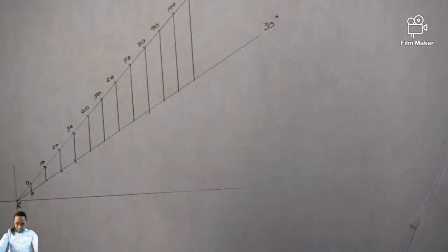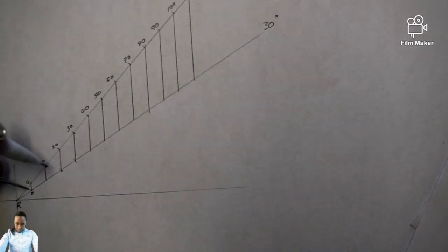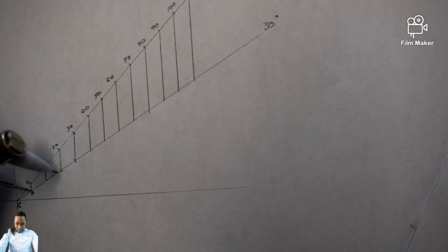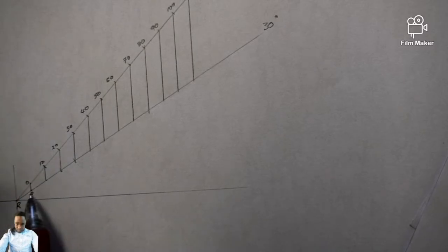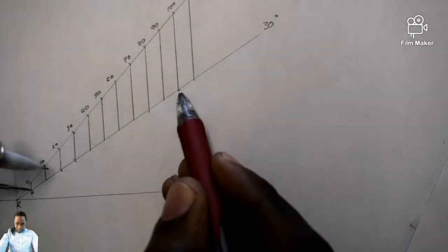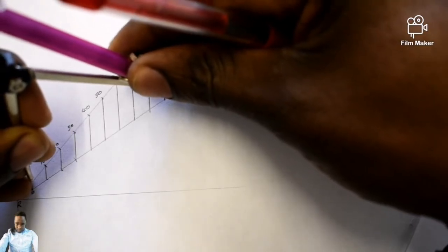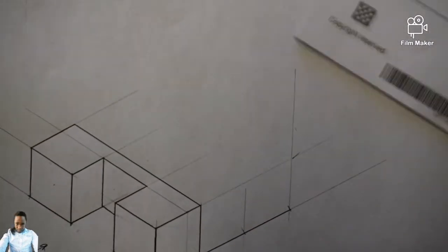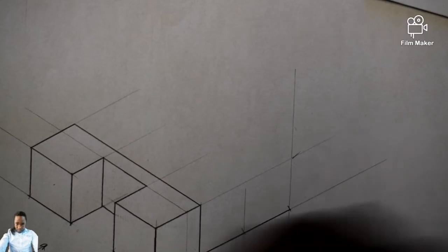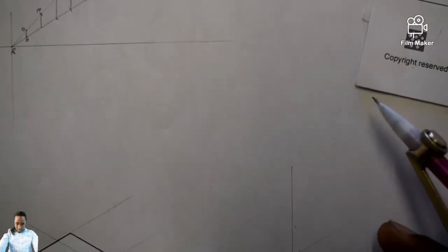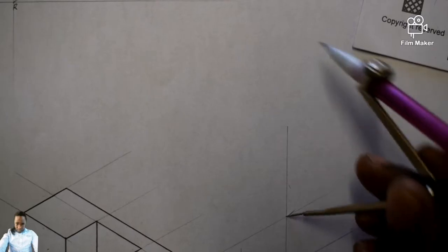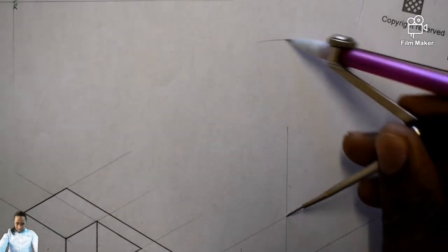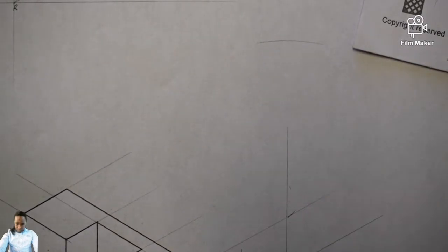So along the line of 130 degrees, I can put my drawing compass or divider at 0.0, so my 100 millimeter is that one, and I can simply open it to 100 millimeter. There is my 100. So now, without disturbing my drawing compass, I come and measure it right here. From here I can just strike an arc that's going to be like this.